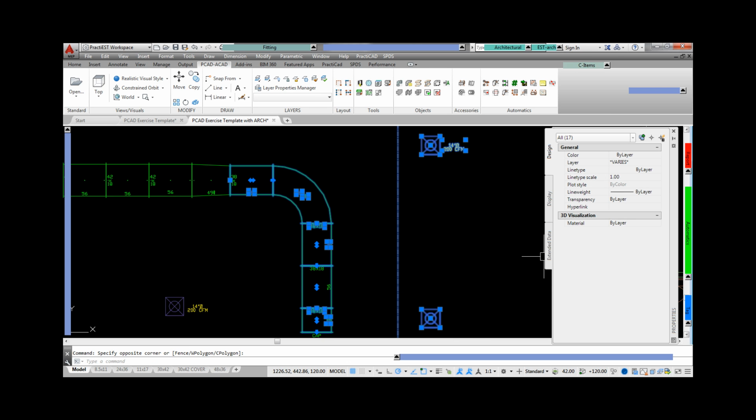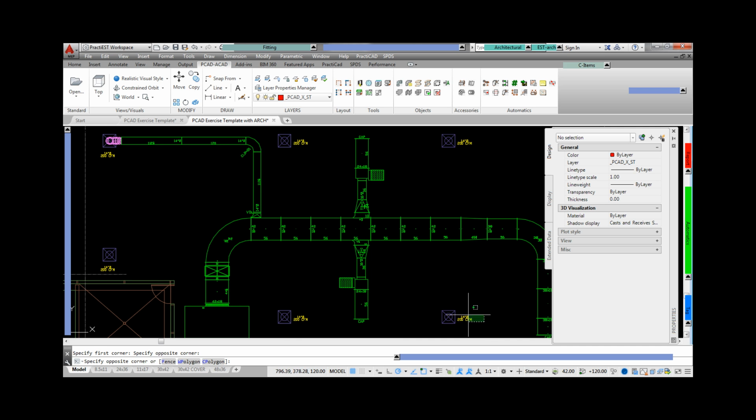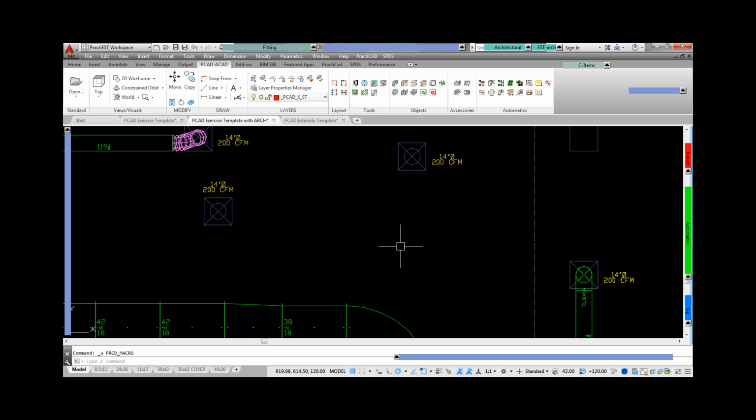Now we'll do one with spin collars as taps. We simply click the grills we want to use, select the fittings you want to route to, and it auto-fills immediately. Watching this next example use conicals, you can also see that we can window an area and PractiCAD will route to them all at once using the fittings nearest the grill. You can run as many of these at once as needed, and there's truly a lot of scenarios to choose from. In this next example, we're choosing between two choices.